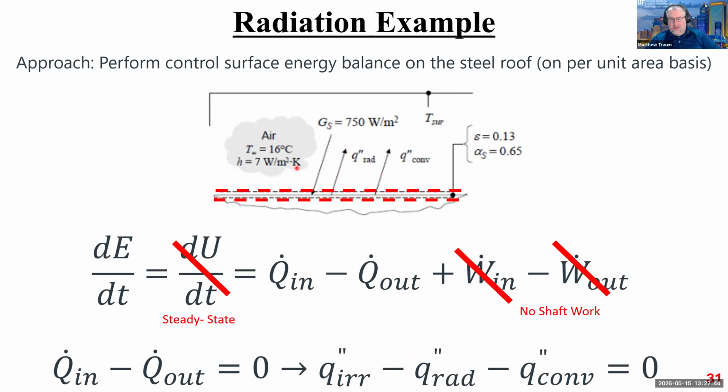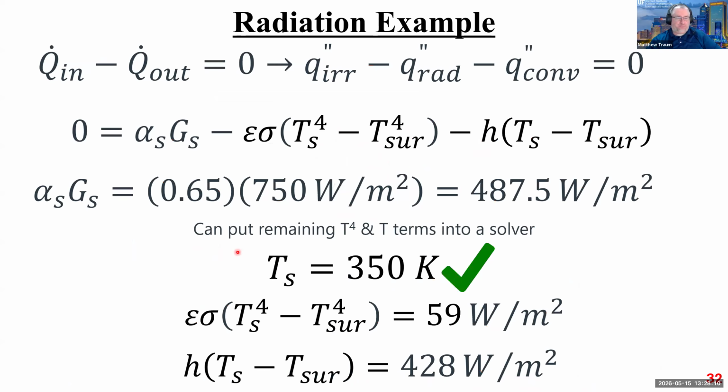So this sun is going to heat this thing up. It's going to get hot and it's going to start convecting to the surroundings as well. And I'm given all the parameters to calculate the convective heat transfer coefficient. So because energy is leaving through convection, this value is also negative, right? So when I sum them up in this way, this is plus, this is minus, they're equal to 0 because there's no stored energy in the system. Okay, steady state. All right.